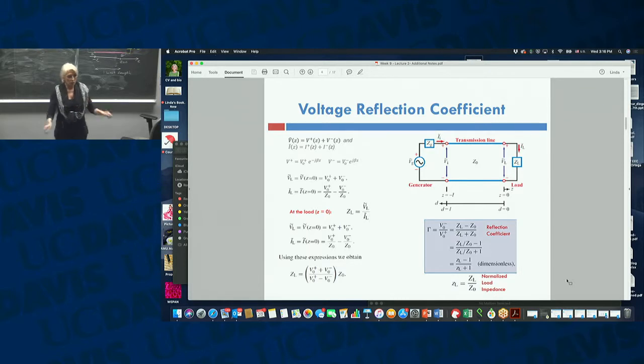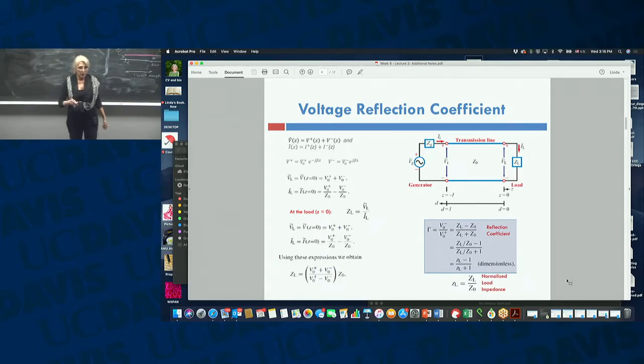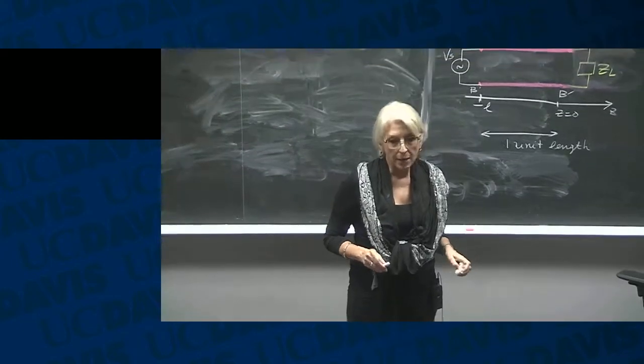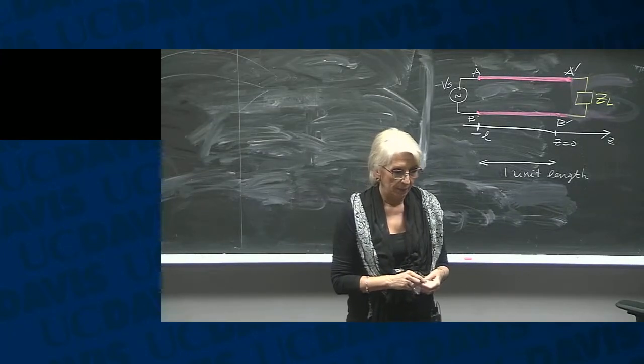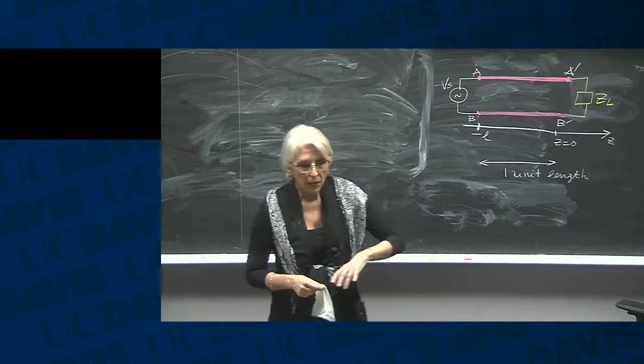That is the norm. And why did we select 50 ohms? Because lines with 50 ohms have relatively larger geometry, still very small relative to the wavelength, so their losses are not very high. If you go to higher impedances, you will see later, you shrink the dimensions of the strip of the microstrip, and you increase your losses. So the prevailing value is 50 ohms.